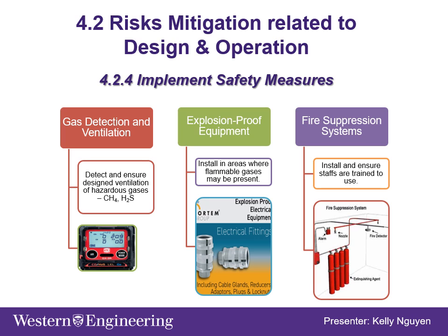With regard to immediate safety measures, it is extremely important in an anaerobic digestion system due to the risk of hazardous gases such as methane and hydrogen sulfide. Gas detection systems and proper ventilation are essential to prevent the accumulation of these gases that could lead to explosion and health hazards. Use explosion-proof equipment and electrical fittings in areas where flammable gases may be present. Ensure all equipment used is certified and meets safety standards.